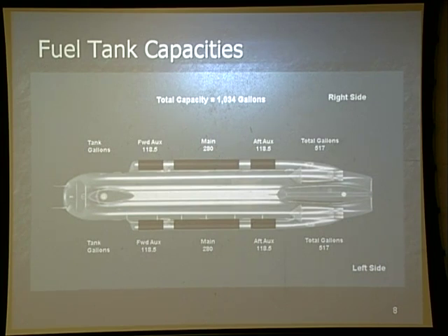But everybody makes a big deal about that 4-gallon difference. It's really only a training tool. Because reality is, as long as we pressure refuel the tank or the system, that 4-gallon difference between the left main tank and the right main tank is really irrelevant. What causes the 4-gallon difference? This is a trivia question, but they like to ask it, so we're going to make sure you know the answer. The tanks are interchangeable between the left side and the right side.